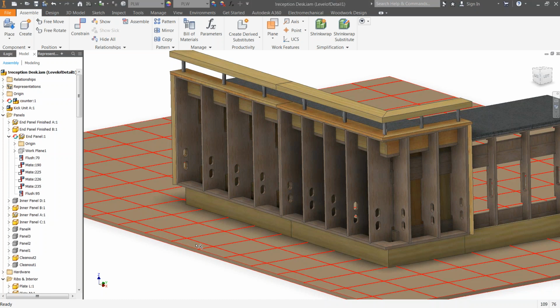In this particular world, you might find that your manager comes to you and says, Steve, I need solid blocking between the ribs, because I need to screw something through the panel. I need a handrail of some sort, and I can't possibly just go through the side panel. It needs to be blocked. So I have two choices. First choice would be to put individual blocks through everything here, which would take a lot of labor and a lot of time. Or what if I put a horizontal rib through all of these at once? Well, that makes the most sense.